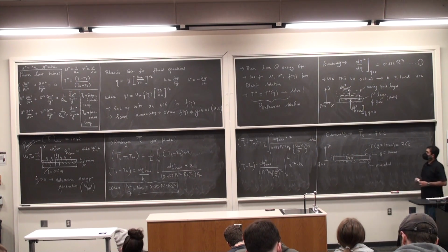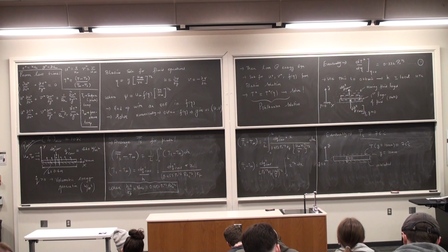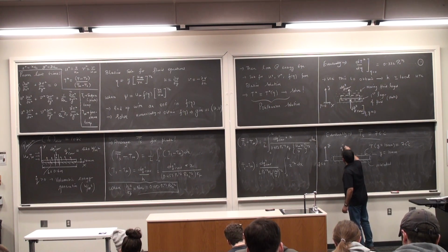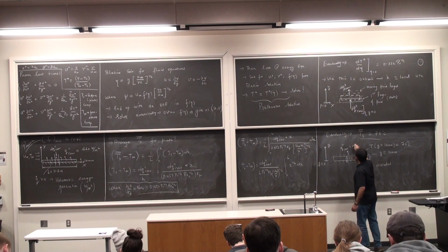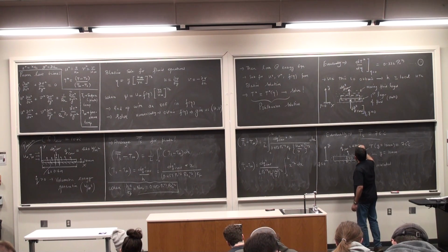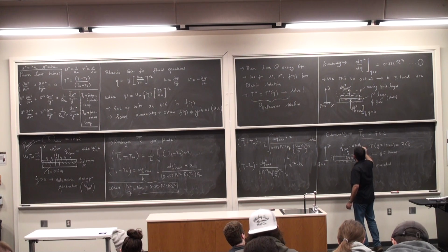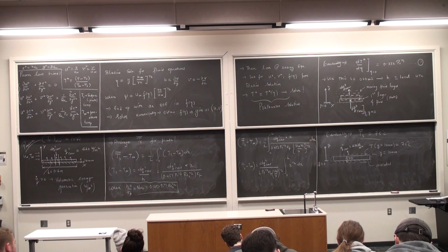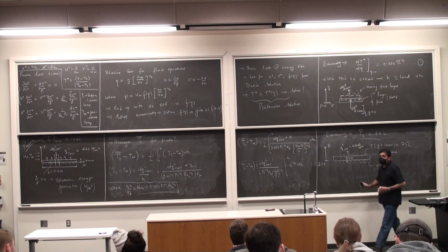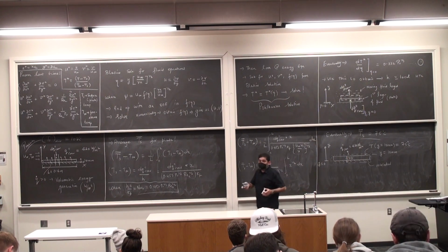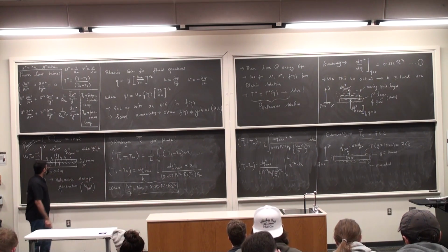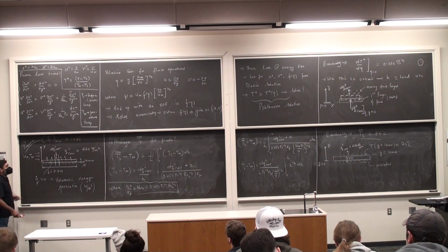So I'm going to draw a control volume, and I have the following entries. I have Q double prime convection given to me, 420 watts per meter square, taking place over the surface area of the plate. I have the volumetric energy generation. The bottom is insulated. Energy balance tells me that the following equation is going to hold true. And now I'm going to erase this particular part.